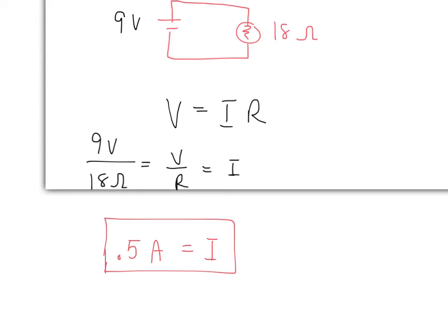What is the voltage law in series that we just wrote down? The sum of the voltages. So if one bulb uses 2 volts, another uses 3, another uses 4, the last one would have only 2 more volts to give you 9 total. So each bulb uses a different amount of voltage. You don't know what that voltage is yet.